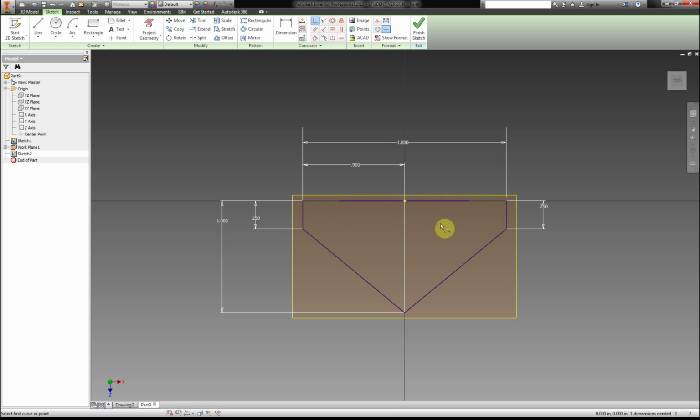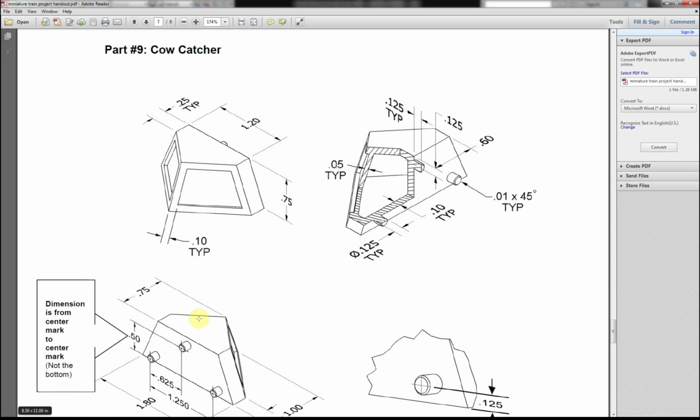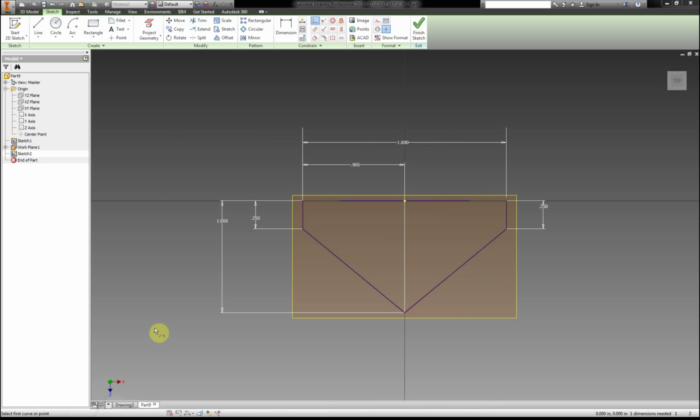The reason for this is you want everything to line up properly, because this cutout right here, if you don't line up everything properly, it won't actually let you create a sketch on that surface. So our first line is going to be 1.2 inches, and our edge right here is going to be 1/4 inch.